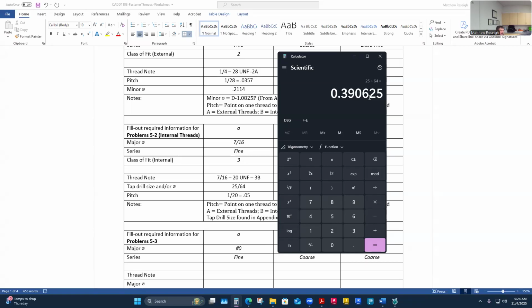There is no guessing game here. This is an internal thread situation. I've got a 7/16 bolt in my hand, and I need to cut some threads for it to thread into. I'm not just going to randomly pick something smaller than 7/16 to allow threads to be cut. I'm going to specifically pick this critical measurement of 25/64. I'm going to drill that through, just a nice straight drilled through hole with no threads. It's just a drill hole. And that's how they cut threads.